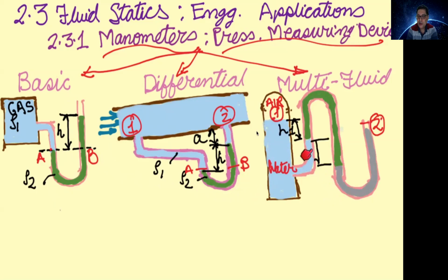So when you connect this U-tube manometer, since there is a high pressure which is created by the air at the top, the water goes inside this U-tube, and the manometric fluid, there is a change in the height by this H2. The difference of the free surface of the water and this location is represented by H1. This is your H2.